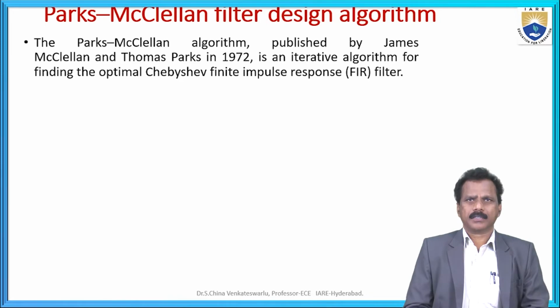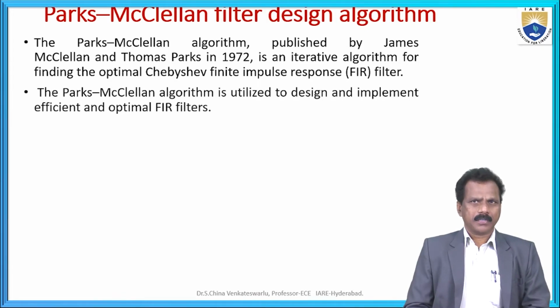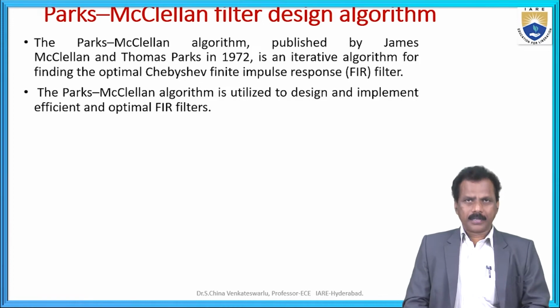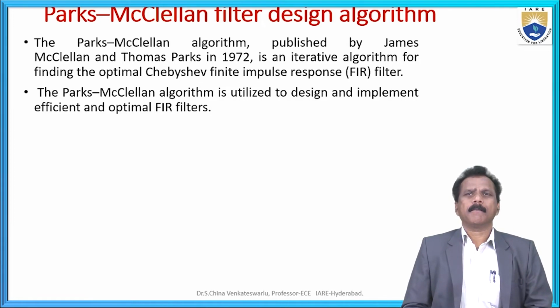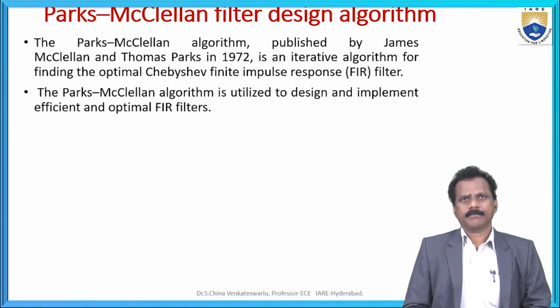This is the background of the Parks-McClellan filter design algorithm. It is utilized to design and implement efficient and optimal FIR filters. But when using the windowing technique for non-recursive filters like FIR, we are unable to receive the optimum response. That's why we have chosen this algorithm.